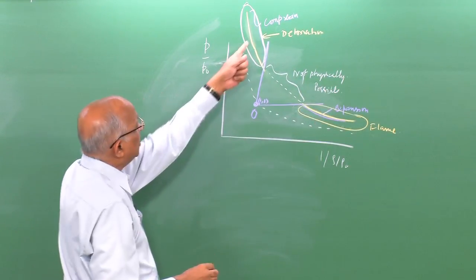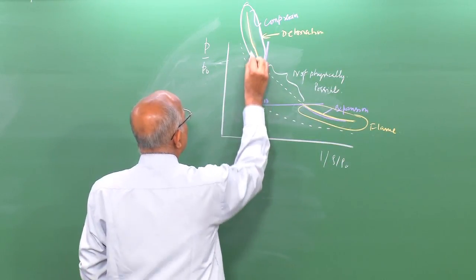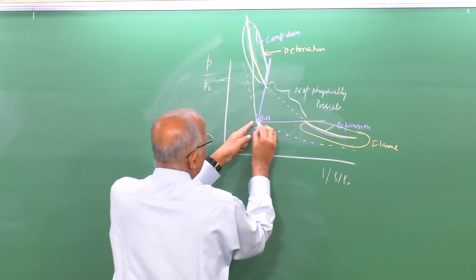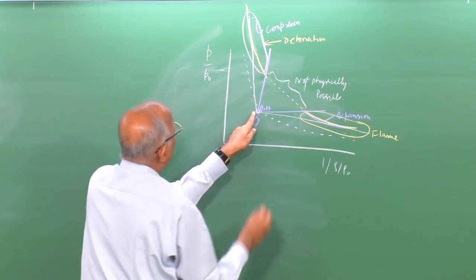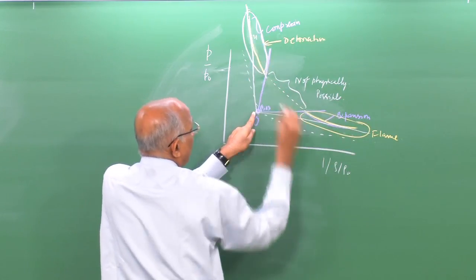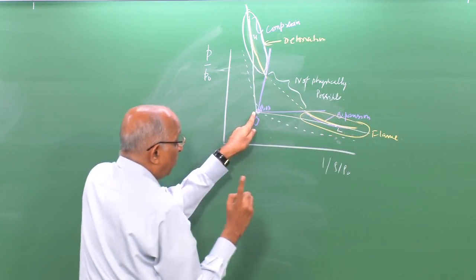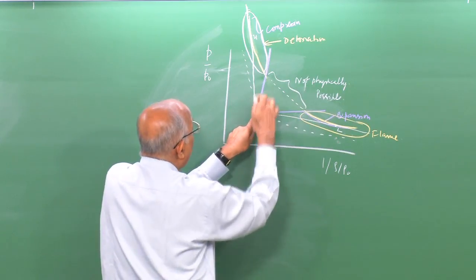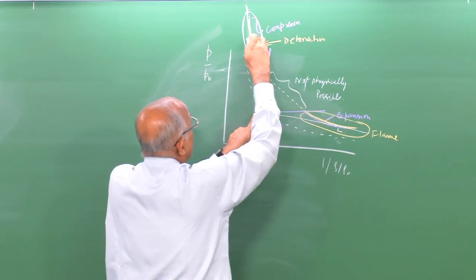Now, we come back to this particular location. Let us plot the velocity. I have the velocity over here, tangent over here. This gives me the minimum velocity. I also have the maximum velocity for a flame over here, and therefore, let us say the point is over here, upper point over here. I have a lower point which is tangent over here. Mind you, we have been plotting tangents earlier also. Maybe from the initial point I have the shock Hugoniot, I have the reaction Hugoniot, I plot this tangent.